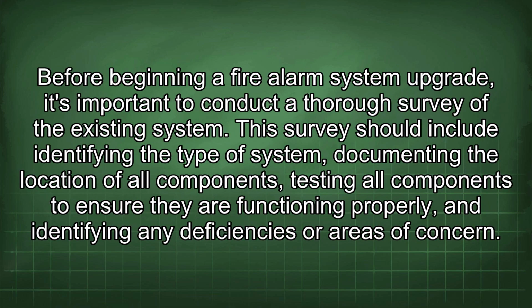Before beginning a fire alarm system upgrade, it's important to conduct a thorough survey of the existing system. This survey should include identifying the type of system, documenting the location of all components, testing all components to ensure they are functioning properly, and identifying any deficiencies or areas of concern.